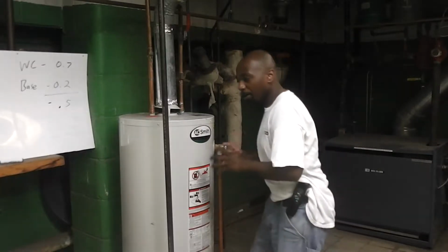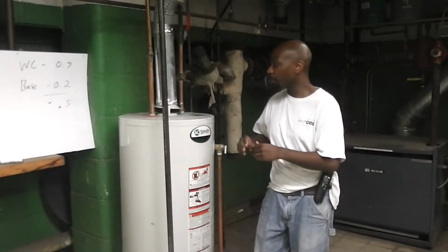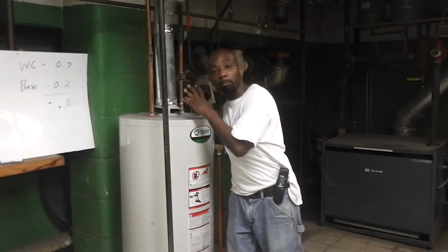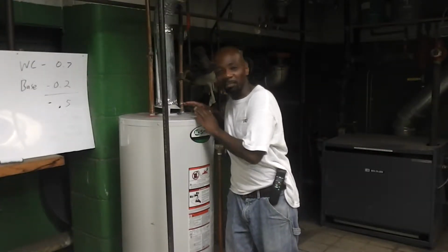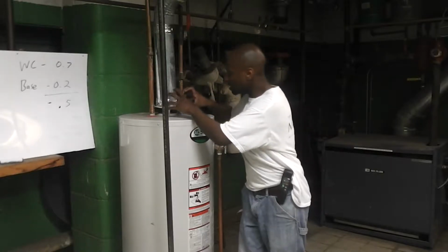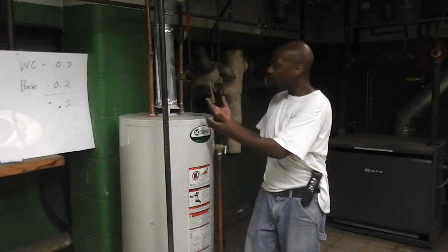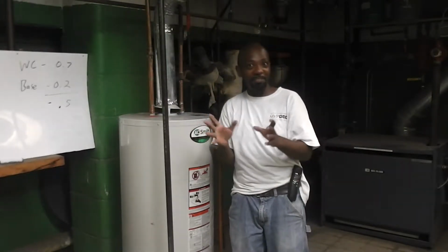So right now I just fired the DHW up. If you notice, I'm turning on the combustion appliance with the least amount of BTUs first. And where am I testing on this thing first? Right now, this thing's going to start spraying out some gases. I'm going to wait about 60 seconds. So far, about 15 have passed.